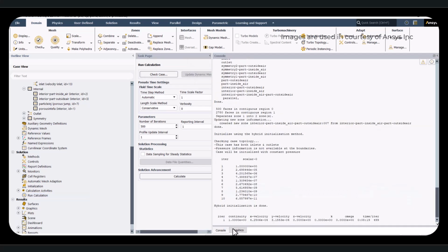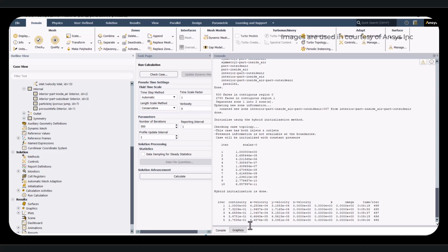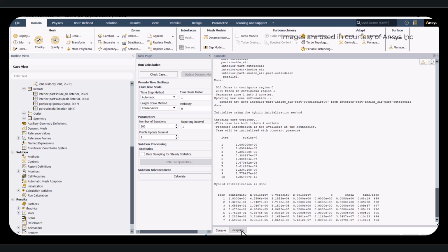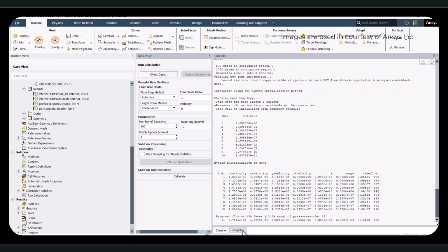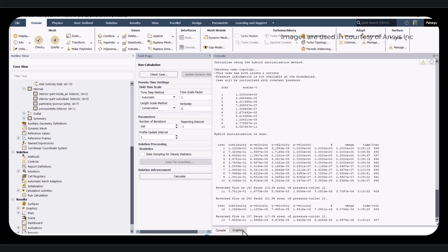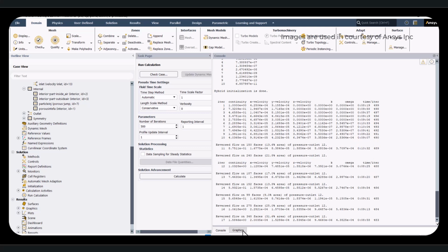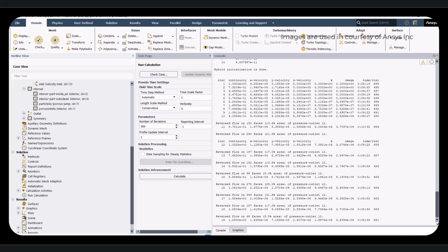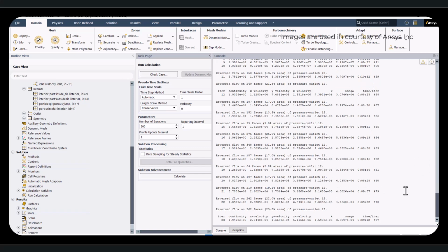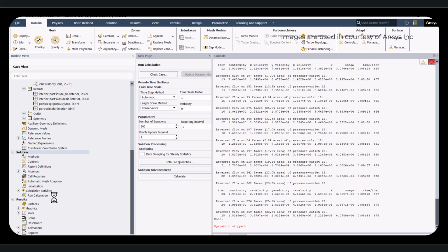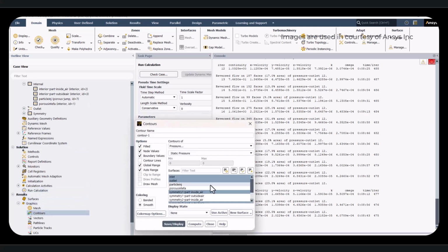So we have not activated any discrete phase modeling. Once the steady state is performed, then we can activate the discrete phase without running the flow simulations anymore. That would save the time and the computational effort also. It's just for demonstration purposes. I'll stop all, and we are not bothering about the convergence and everything. And we'll check how the contours look like.